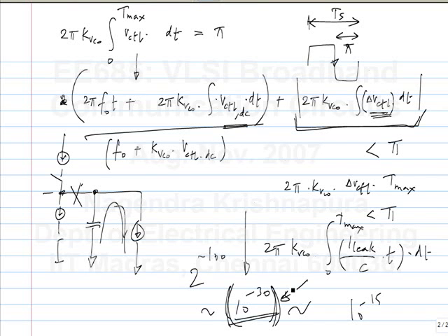So the bit error we get from the Q function, Q of the signal to noise ratio, that is the raw bit error rate. If you see the bits that are transmitted here and the bits that are transmitted there, how much will they differ? Now they can differ by let's say 1 part in 10 to the minus 9, but then you can have additional coding that will make sure that the error in the total information bits that you are sending is maybe 10 to the minus 15 or something. Okay. By adding redundancy, you can do all of that.